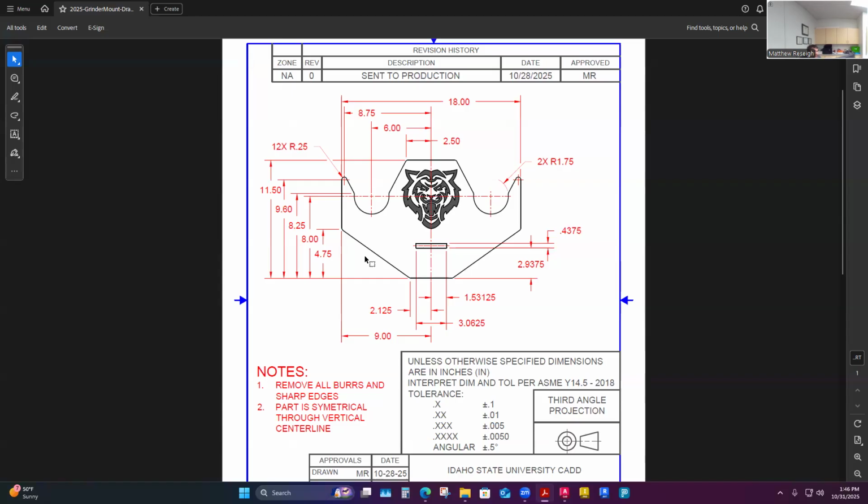So let's see. I'm going to have this up on my other screen, and I'll be referring to it. But first, initially, I'm going to build this boundary. That's an 18-inch by 11.5-inch boundary. Then I'm going to probably put some center lines on there. And then I'm going to come back here and start pulling some of these dimensions from the center line and start putting in the visible, machine-cut lines that we need here. So let me go do that.